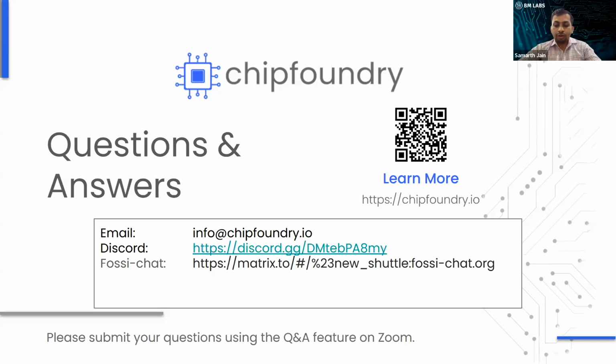So when it is fresh out of the foundry, you will read everything as zero. But once the initial forming is done, and you need to form only once, the data can be random, depending on what was stored previously. So we give you the flexibility to play with the memory and just provide you a digital interface. You can write your firmware to take care of those things.